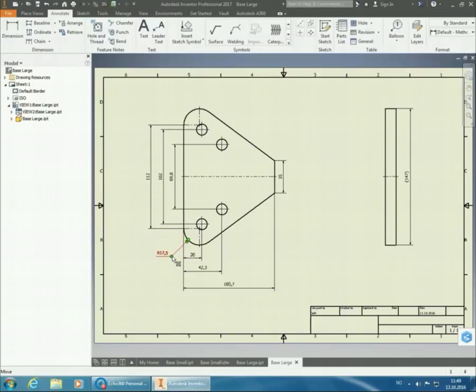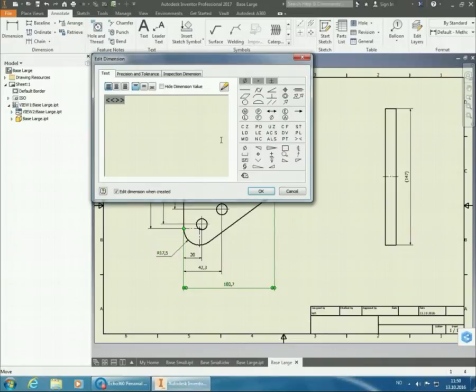For this dimension, we should actually add the reference for this one also, because it is really controlled by having the 35 millimeter there and having the 112 between the center points, and the fact that it's going to be a tangent on the radius there. So it's going to sort of lock it in place anyway. When you start following the outline of this one, the length is actually defined by other dimensions, not the total length dimensions. So we're just putting in a reference point here.